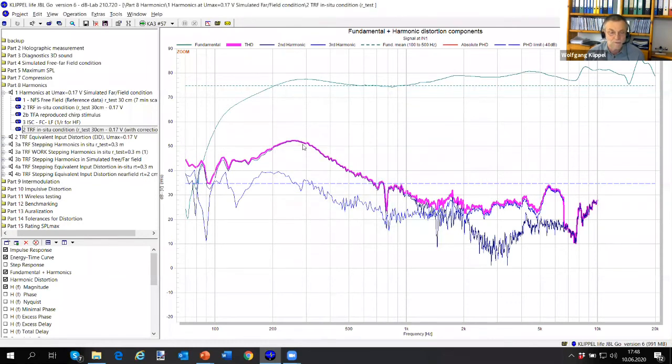We have a maximum close to the resonance frequency. And if you remember right, that could come from stiffness and it could come from BL, and then it's decaying here. And if you look very carefully, it's decaying more or less with 12 dB per octave.